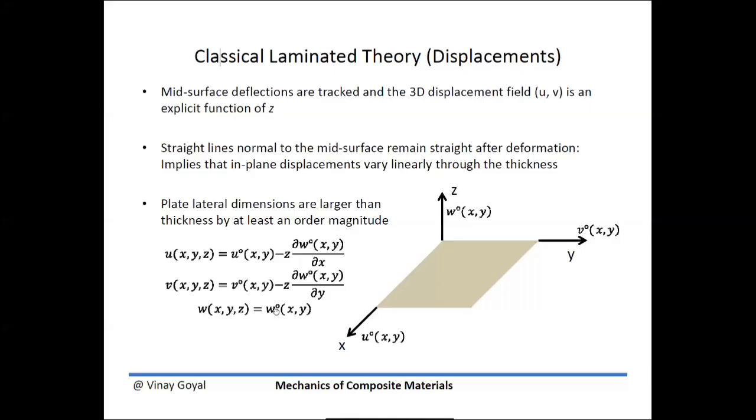That assumption makes sense because if you have a thin plate and you deform a thin plate, you don't expect significant changes to the thickness of that plate. As a consequence, it doesn't matter where you are in the thickness of that plate, the deformation through the thickness will be equal to the deformation at the mid surface of the plate. Okay. And so the question is why we arrange the equation in this manner.